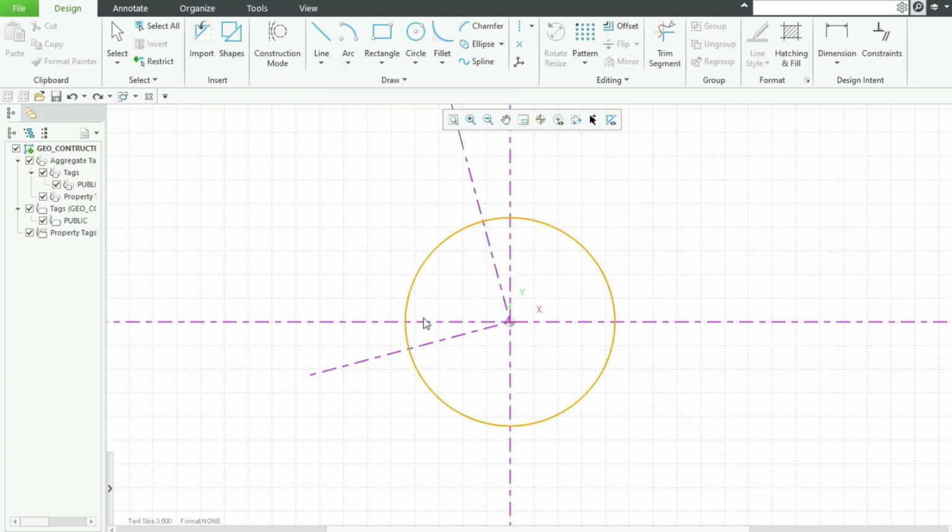This one, let's keep it 16 mm so that we can have a track, and this side also 16 mm. Now let's bisect this line by taking this as a center point, something above the midpoint. Let's keep it 23.